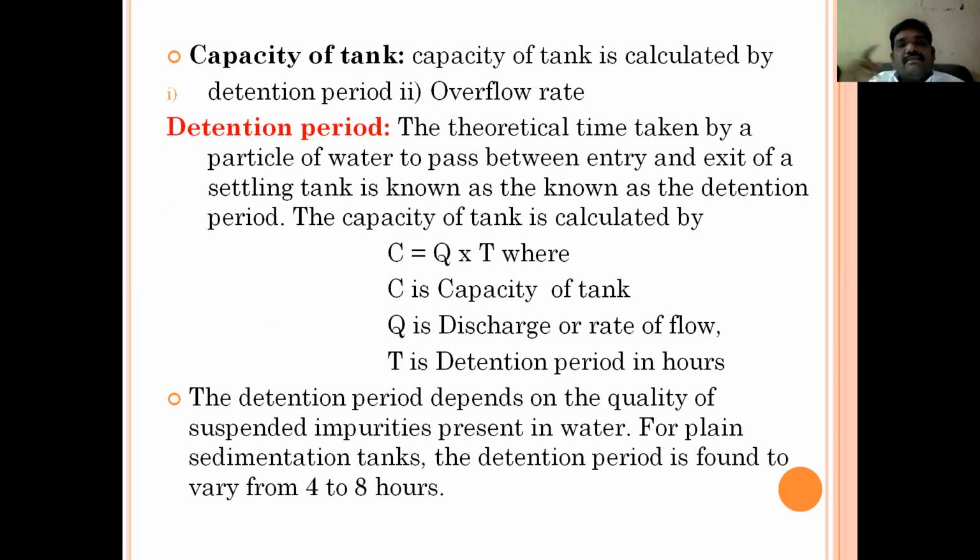And the other one is capacity of tank. The capacity of tank can be calculated by considering the detention period and overflow rate. See, what is the detention period here? The theoretical time taken for a particle of water to pass from entry to exit of a settling tank is known as the detention period.